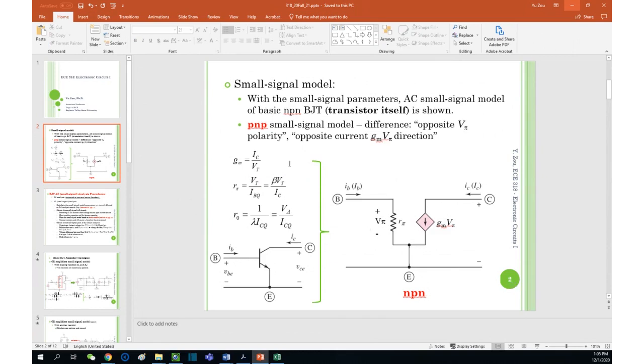And the three small signal analysis parameter equations are listed here. We have three this time because back in the MOSFET, we only had two. Everything in AC analysis begins with this. You need a circuit, and the circuit begins with the small signal model of the transistor, and then you extend the circuit terminal by terminal. That's why this is so important. You want to use this as a handout, print it out, and have it ready all the time.